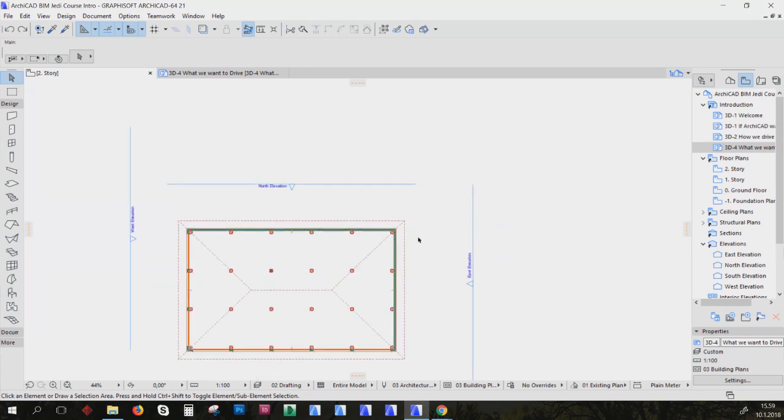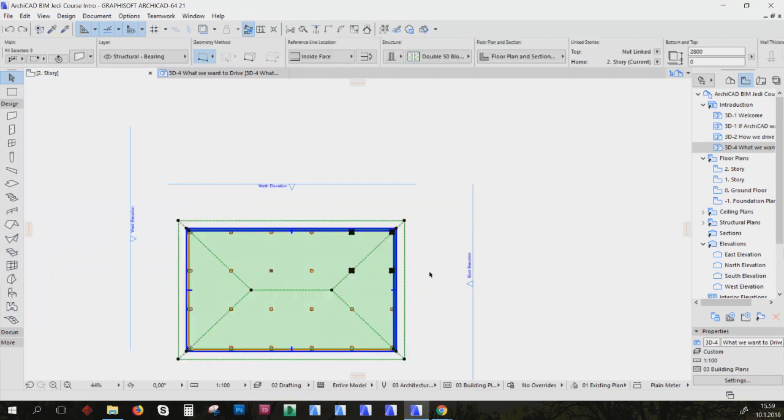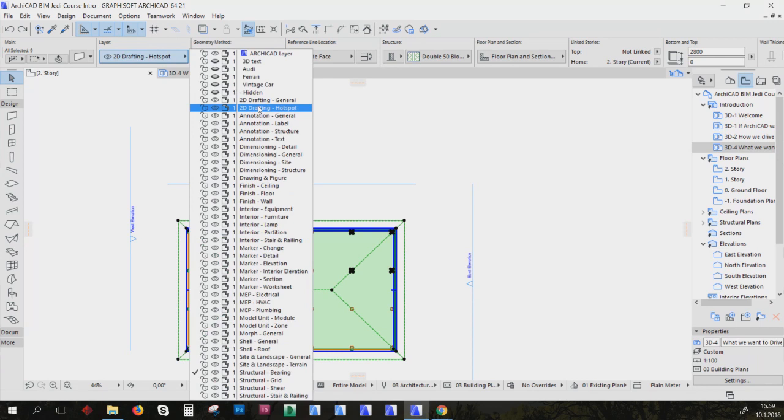Then we've got now that one. Sometimes they used to have a little icon on it, but they took it out in 20, and that's where you want to change a parameter, so a layer, across multiple items that aren't on the same type of thing. If you grab a wall, a column, and a floor, and you want to put them all on the same layer, but they're all on different layers, you can't just do it by grabbing them and changing it in there, because it will only change what's active for the last selected object.